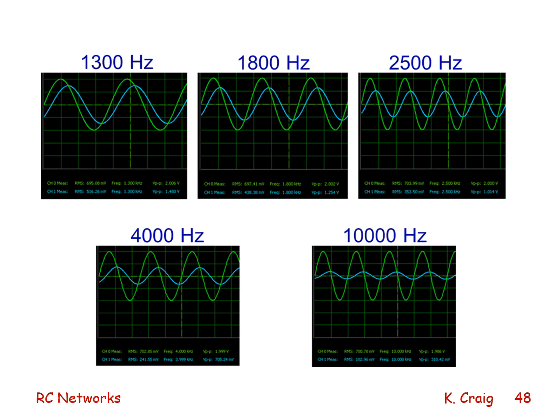Then as I increase the frequency, you see that the amplitude ratio gets smaller and smaller, and the phase angle gets larger and larger in a negative value. But the phase angle will never go past minus 90 degrees. However, the amplitude ratio will continue to get smaller and smaller.